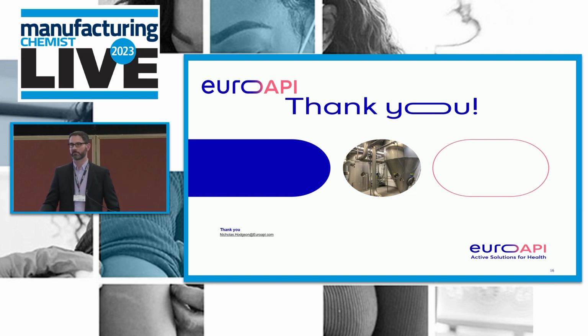You can collect it directly from the cyclone, just by putting a different catch pot on the bottom. There's no issue with closing the cyclone for a few seconds while you change the container, and then just collect under the new set of conditions, and then either go back to the main collection pot or change your conditions again and go to a new sample. So it's relatively straightforward.